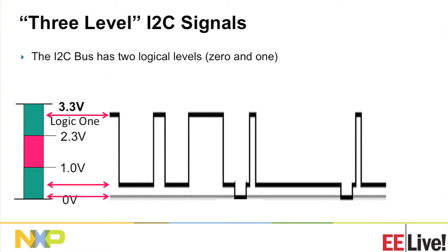It turns out that the way the bus works, there may be an offset on the bus for the logic 0 condition. And this offset may be there as a consequence of wiring resistance, connector resistance, and the physical size of the bus. It may also be there because we deliberately put offset onto some of the parts. And some of you may already have come across that. You find that parts can, under certain conditions, be connected together without any restraint.